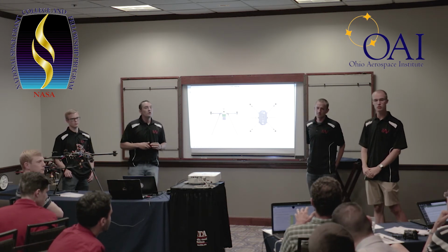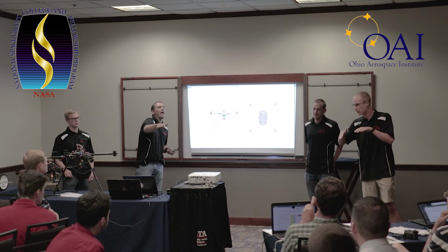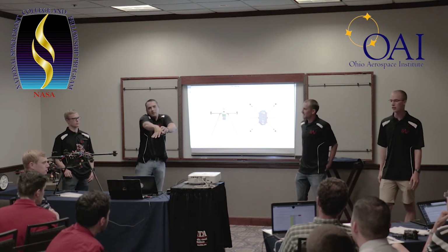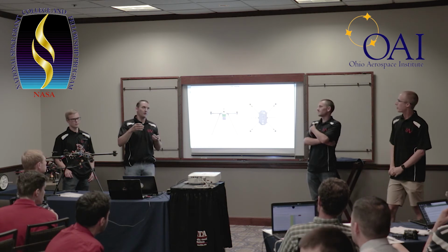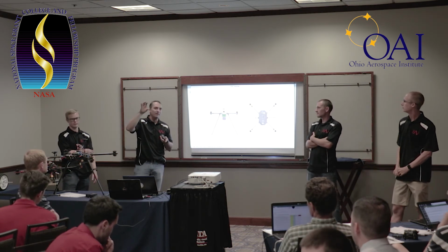Well, your IMU is telling you that something's happening here. It sees the pitch and roll, so it wants to counteract and pitch back. And what you'll see, if you look at the log file, is the output PWMs reflect that.